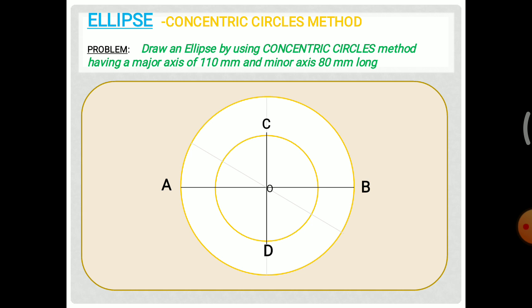Then divide the large circle into 12 equal parts. The circle has 360 degrees, so when we divide it into 12 equal parts, each piece is a part of 30 degrees. So divide the circle into 12 equal parts. So there it is. We have divided the total circle into 12 equal parts, where each quarter gets 3 equal parts. That is, every 90 degrees has 3 equal parts and each part is of 30 degrees.